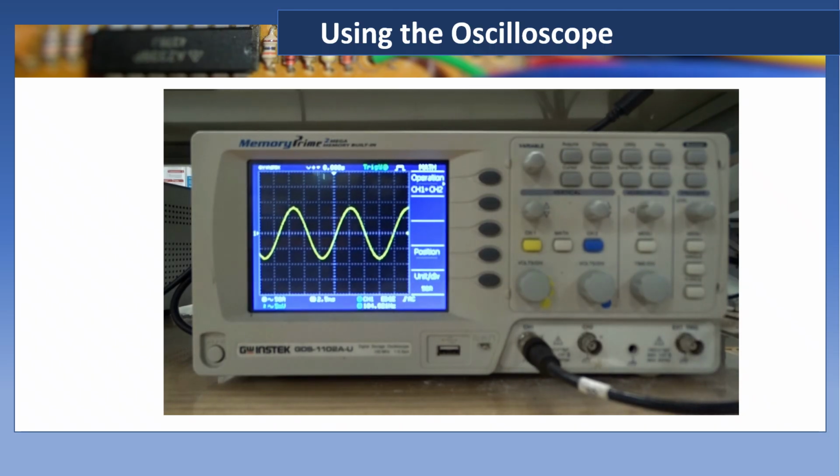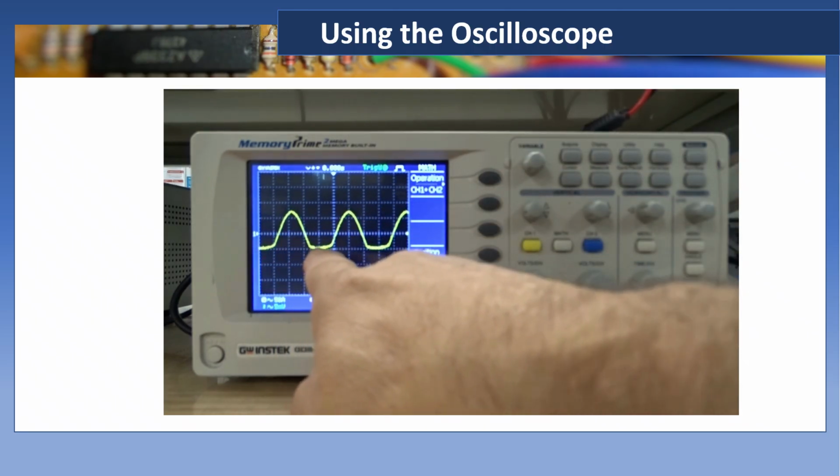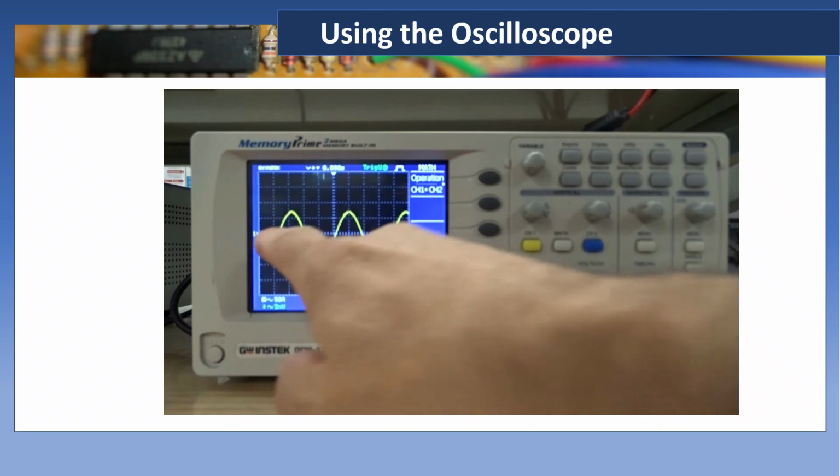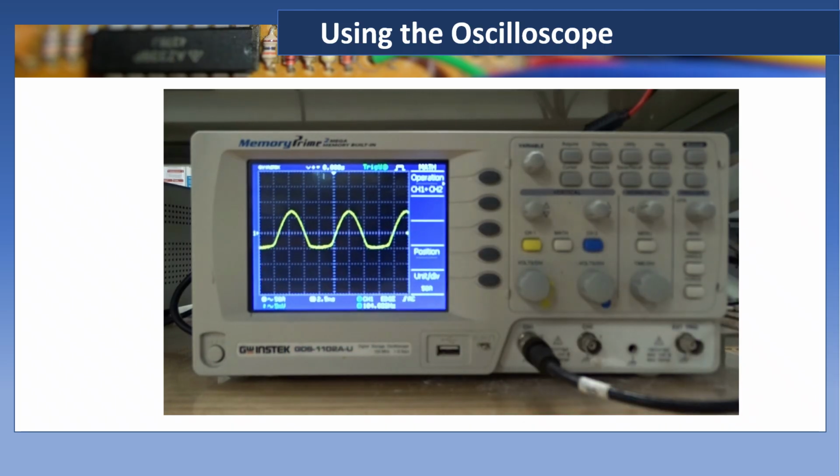So then what we're going to do, right now I've got the circuit set up on my board, but I've left it open. I've not closed the circuit with a diode, so I'm going to put that back on. And now we're running through the 2 diodes as shown on the lab. And notice that the bottom of our sine wave is now being clipped. If I take that off, it goes back to our sine wave.